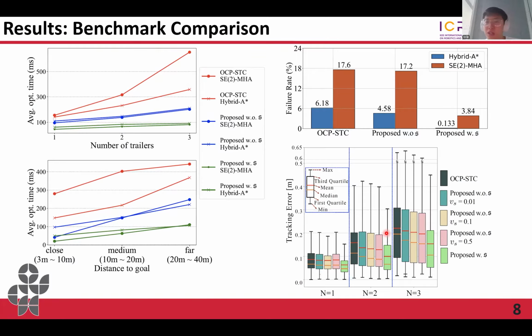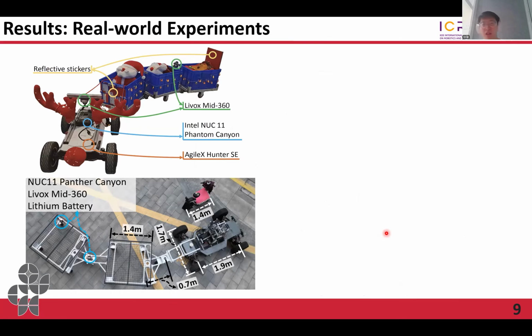We attribute this to the high-order continuous polynomial trajectory representation. Compared to methods employing discrete motion processes, our approach essentially guarantees the continuity of the state and finite-dimensional derivatives, making our trajectory closer to the real physical motion process.